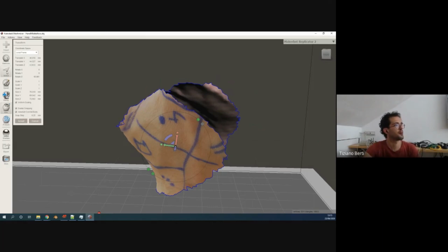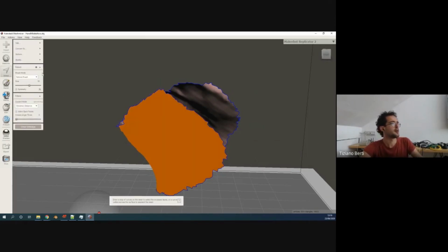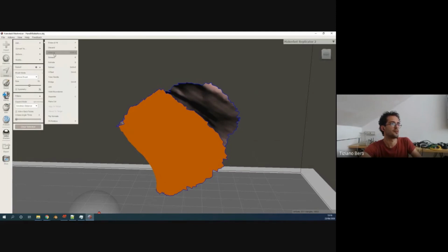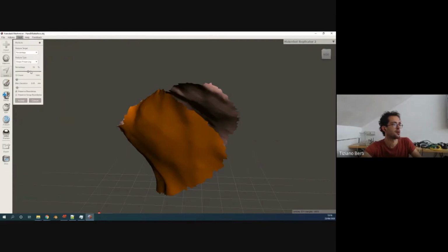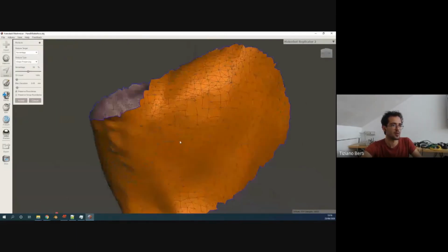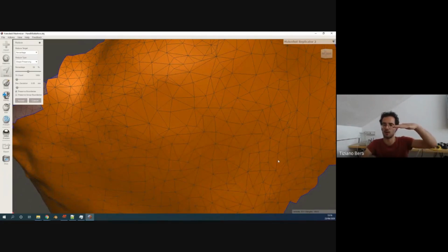The part with the pattern is actually not so problematic. If we have this random polygon, most of them are correctly aligned, and we will just have some random one that is completely horizontal, and that will be a bit more problematic to print with the FDM machine.